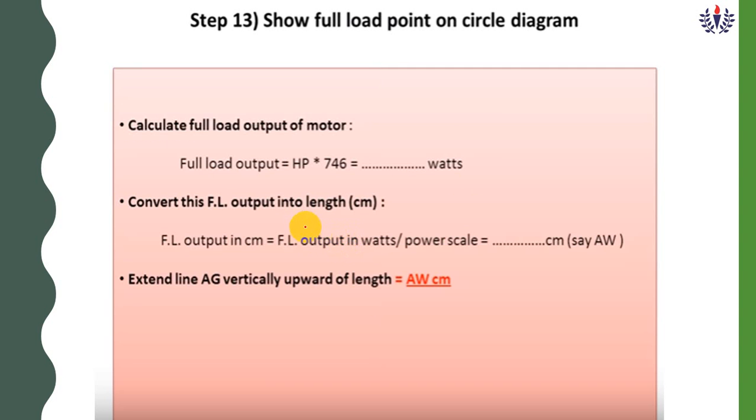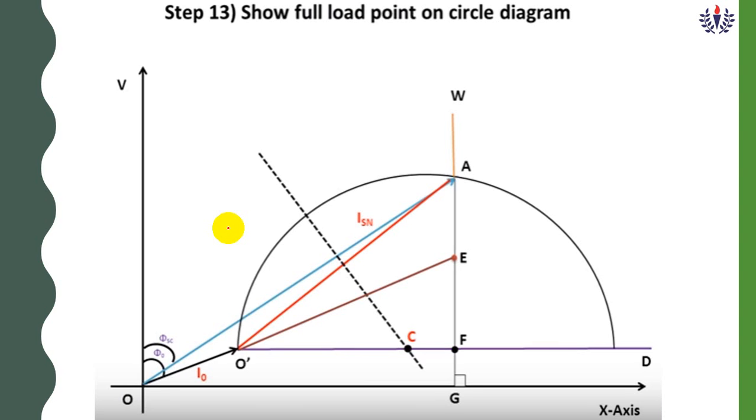Then calculate the full load output, equal to HP into 746, because 1 HP equals 746 watts. So 746 into HP equals watts.